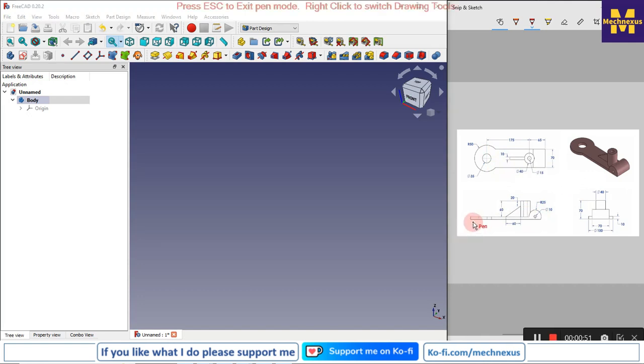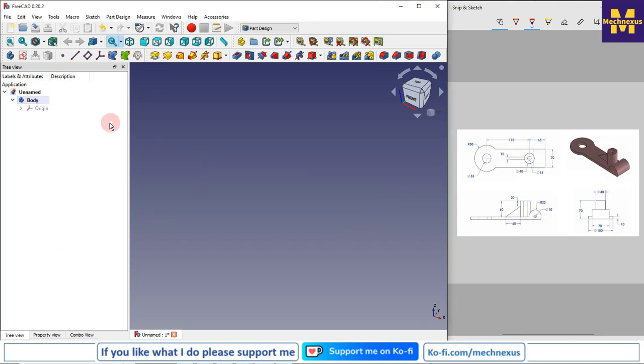So first we will make this profile like this, and we will extrude more than 100 mm, and then we will make the cut on both sides from here and here, and then we will add this boss, and then we will add this stiffener. So let's start. Here I have created my body.